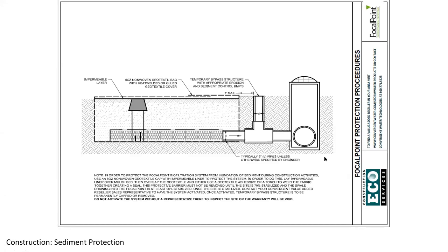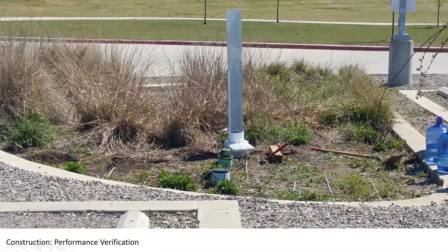And then you can always do an infiltration test. One thing we do is when you specify engineered soil, if you have a flow rate of say 50 inches an hour or 30 or whatever it may be, you can do a simple flow rate test. We have a little hydraulic conductivity tester we take out. This just keeps the contractor honest, and it also makes sure that after you install it, it wasn't clogged from construction sediment or erosion. And if the contractor can't pass it, then they have to go back and install it correctly or make repairs.